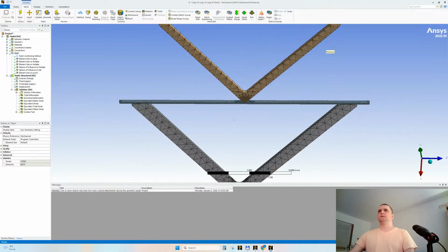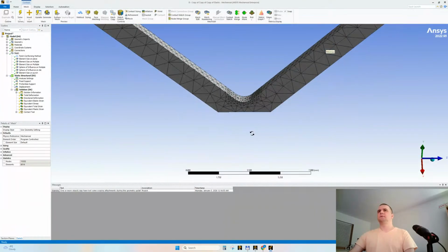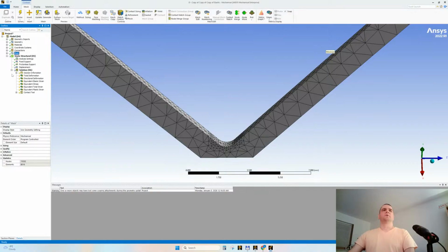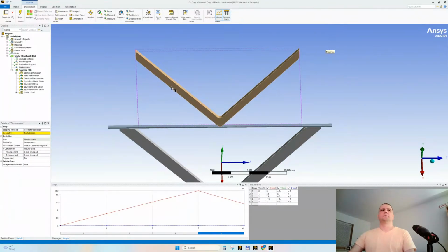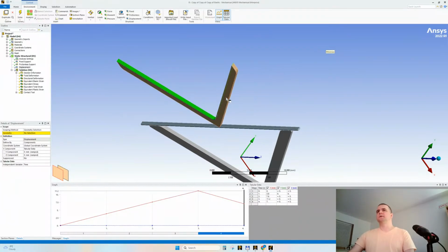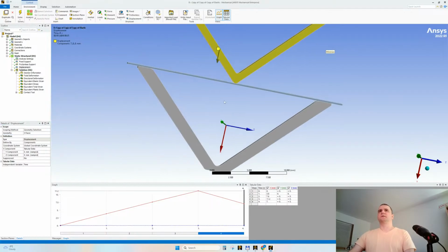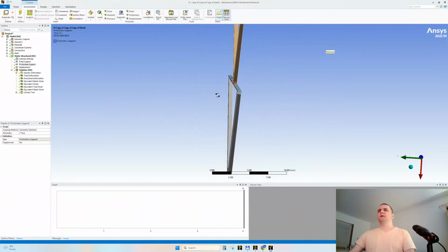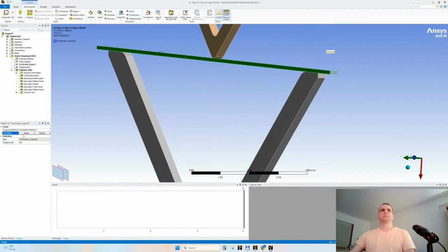You know what? Let's leave it like this. We have half the mesh that we had before, which is perfect according to my desire. What do we push? This, this, this. We push everything. This and this. Let's push it downwards. All right. Yes, again. Frictionless support. Also this face, because you lost a face due to the cutting operation.